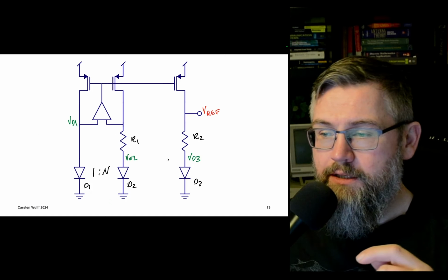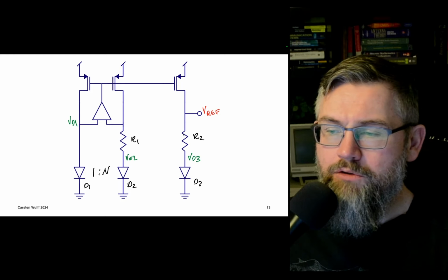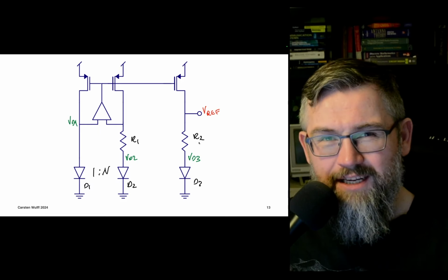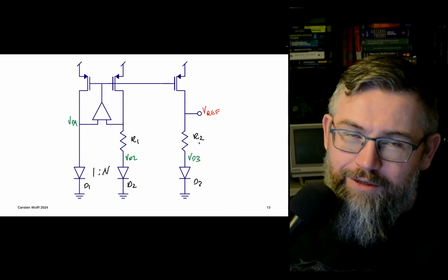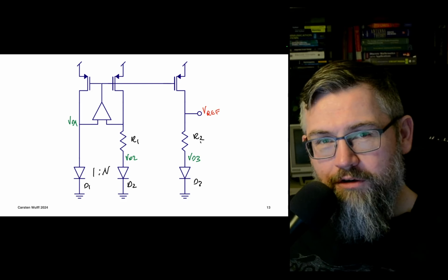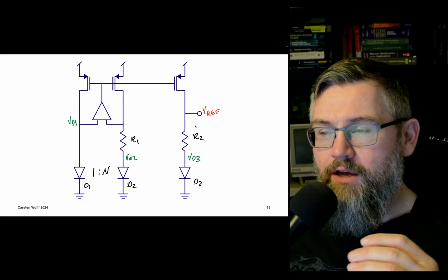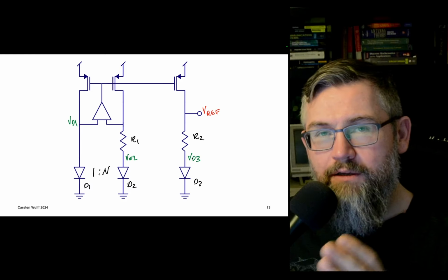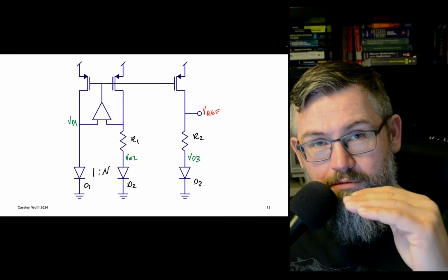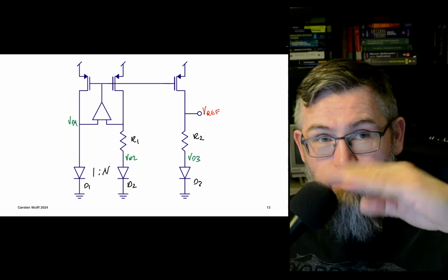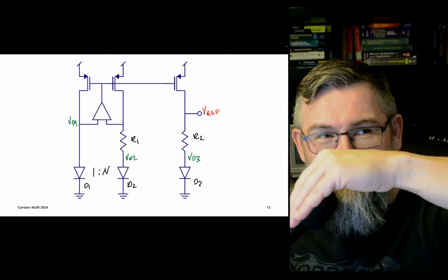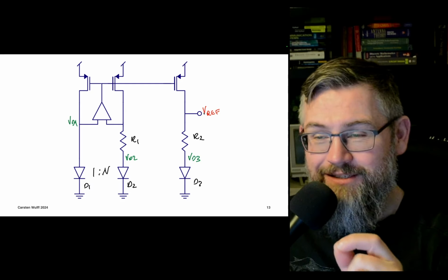The diode voltage usually is on the order of maybe half a volt. So probably between R1 and R2, you're going to have a size difference of maybe 10 or 11 or something like that. The exact values you have to simulate, or you can compute an initial guess, but you need to simulate it. But if you tune R2 correctly, you can get to the point where as temperature increases, the VD3 decreases, but the voltage across R2 increases, and you're left with a reference that is stable. It'll have the second order gradient, like that. And it might tilt a bit depending on corners, but it can be extremely precise.